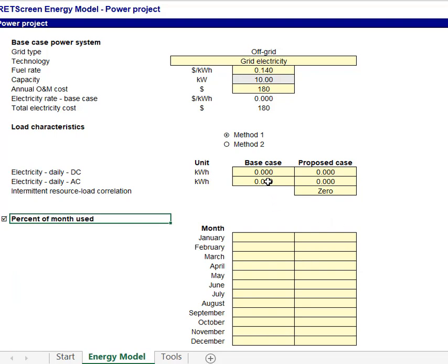So now what I put in here, I put in the month that I used the most. And if I look back at our data that we had on our homework last week, there's 60 kilowatt hours per day. That was our maximum. So I'm going to put in 60. I'm going to put it on both sides. Now here, this is a percent.